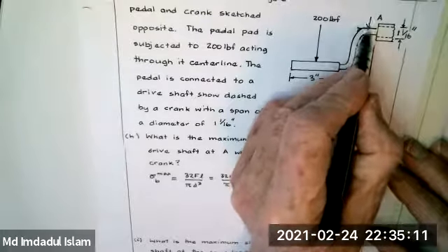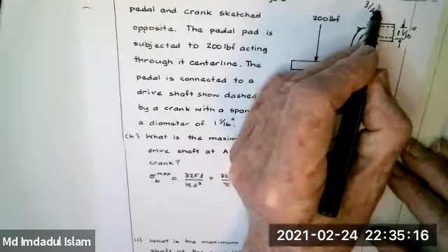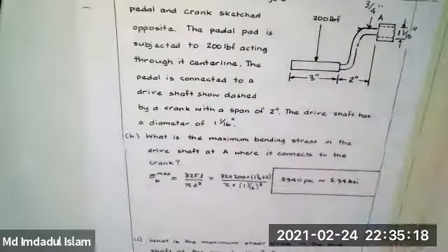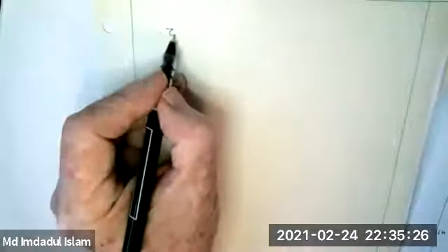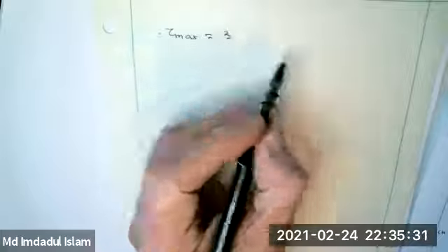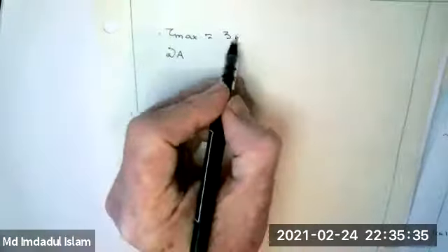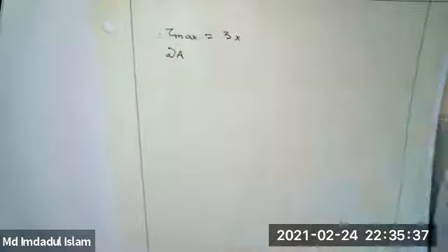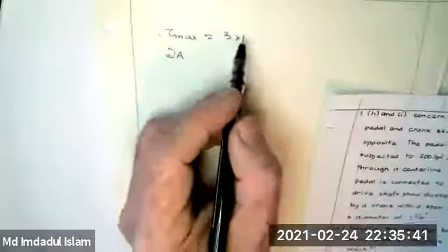And so the force would move in here, and the moment arm would just be 3/4 of an inch if you stepped on it. Now, I'm not encouraging anybody to do that. That doesn't seem like a very sensible thing to do. But even if you did that, that would reduce the tau max. It used to be 3 KSI, the tau max at A, and it would go down because the moment arm has gone down. The moment arm used to be 3.5 inches, and now it's 3/4 of an inch.